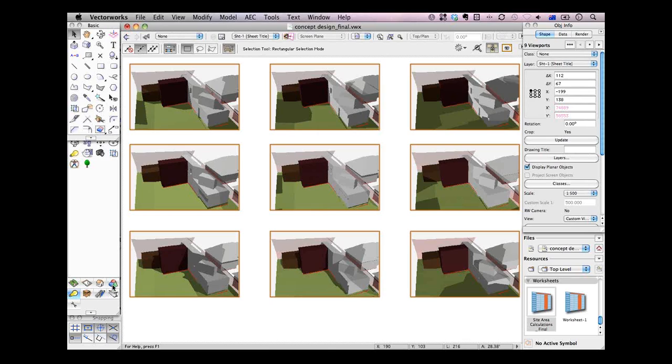Okay, here's another good question. How do I ensure I'm at the right coordinates for the proper lighting? As in, where do I enter the geographic coordinates for the original polygon? I don't think you need to assign the correct geographical coordinates for the polygon, because when you set a sun position, you're saying to Vectorworks at that point, this is my location. Here is my latitude and longitude, and it puts the sun relative to that.